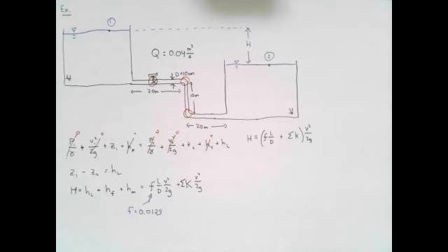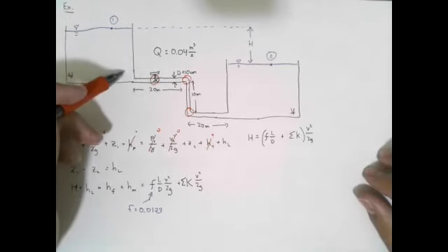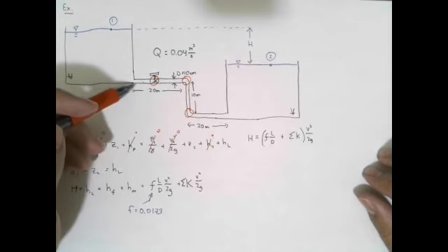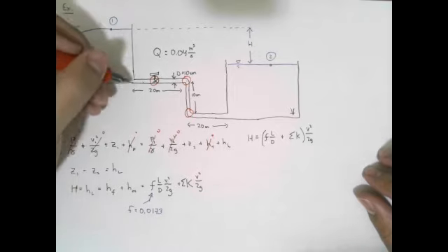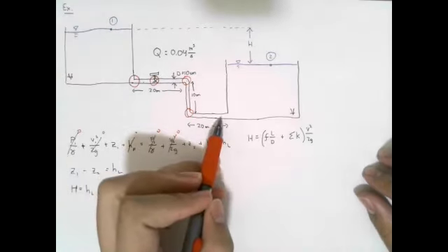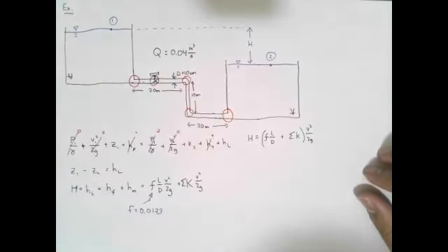What about when the tank turns into the smaller diameter of the pipe? Exactly, right? When the fluid travels from the tank, from the reservoir into the pipe, we actually have a really big change, right? We have a change in geometry of our system. And of course, we have the same thing when the fluid goes from a pipe to a reservoir. So these are our minor loss components for this particular system.